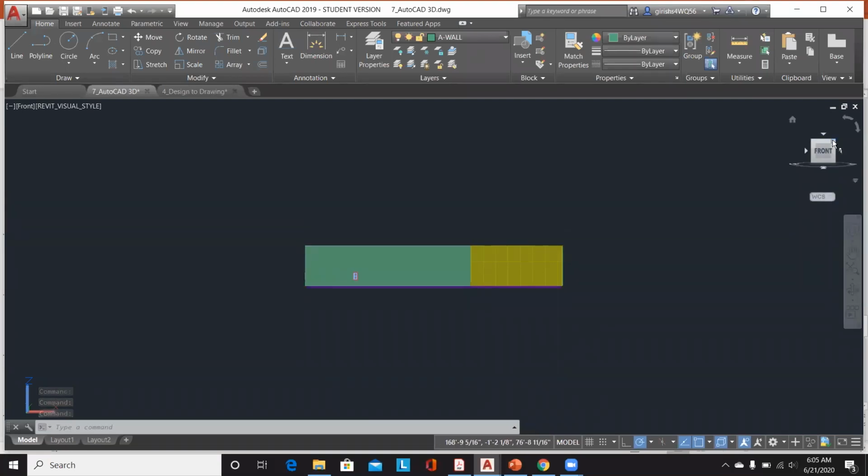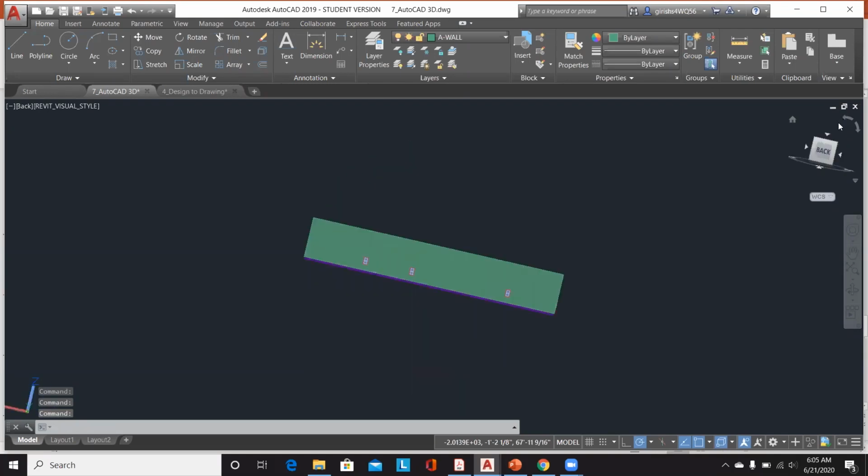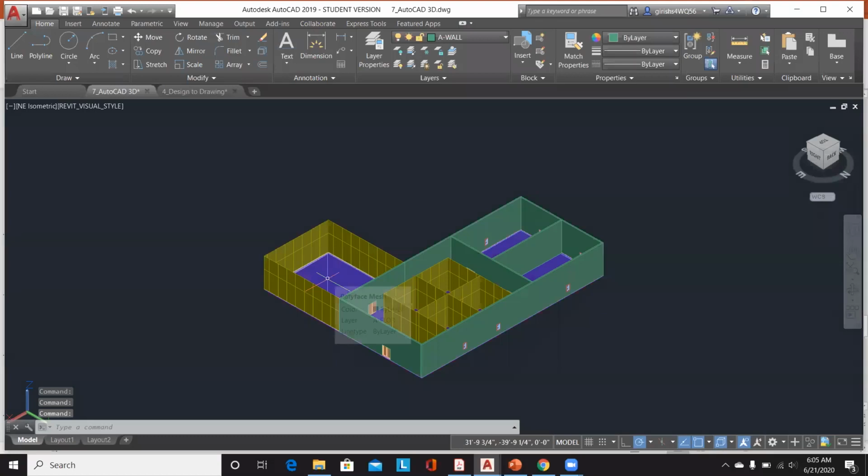You can choose how the building looks from the right and the left, or from the front and the back, and you can choose to navigate the way the orientation of the drawings is marked in your workspace. It will let you create certain elevation views and section views based on the way you set your view cube.